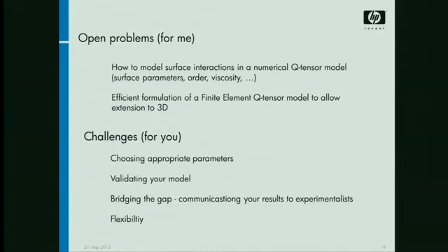At the moment, we're using Lagrangian elements, which are quadratic. Linear elements are no use whatsoever. We have to use quadratic elements at least, but even then, it takes far too long to run the models and get any useful results. It's also much more difficult to get convergence than in 2 dimensions.